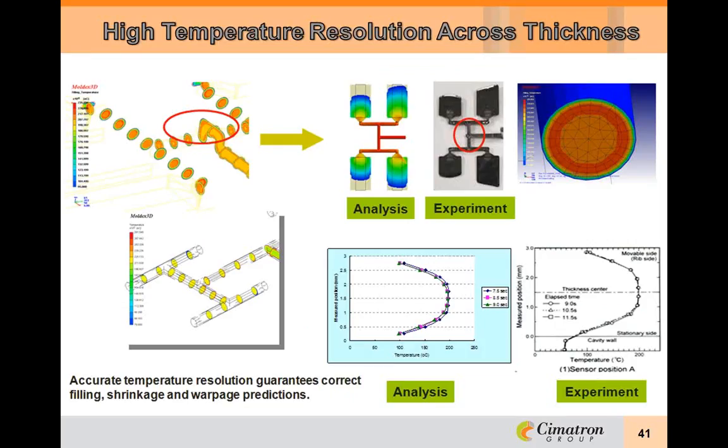Mold-X 3D not only simulates the part in true 3D, but also the runner system. You might question why this is important. The reason is because of what is called shear heating phenomenon. While the material is flowing through the runner system, friction is creating heat. This heat does have an impact on material flow, and the next few slides will demonstrate this.